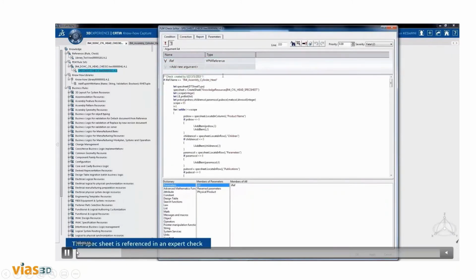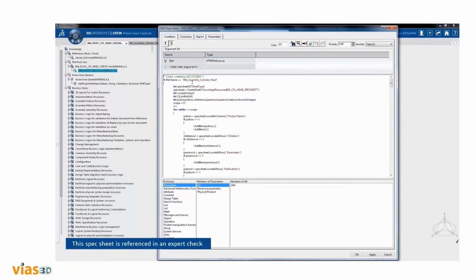So now I want to stop here on the scripting because I wanted to talk about this for a minute, because everybody sees this and gets scared of scripting right away. In the 3D experience, you can use Python scripts, you can use Visual Basic scripts. However, because it's a database and all the objects are already known, writing automation code becomes so much simpler. If anybody's written Visual Basic code before, you have to give every object its name, where it is, where it's located, and what it does. Well, you don't have to do that in here.